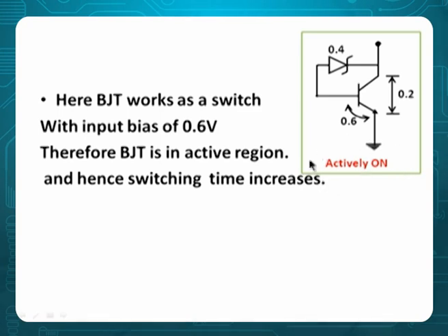That's called actively on. It is on right at the active value, or some people call it non-saturationally on, because without going into saturation, it is on. What a surprising thing. That's why I always say, you are not only doing something outside the device, you are also doing something to the device. And without going into saturation, it is on. So it is easy to turn off. Turning off will be very easy here. That's why non-saturated circuits are faster than saturated circuits.